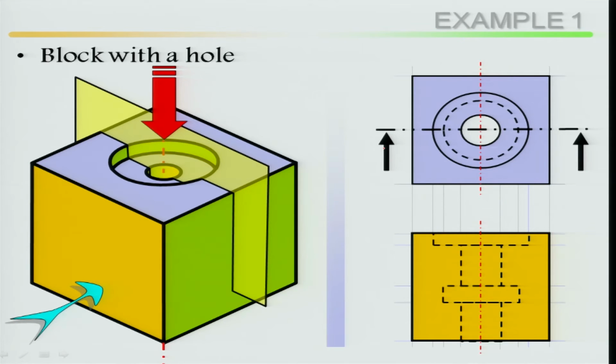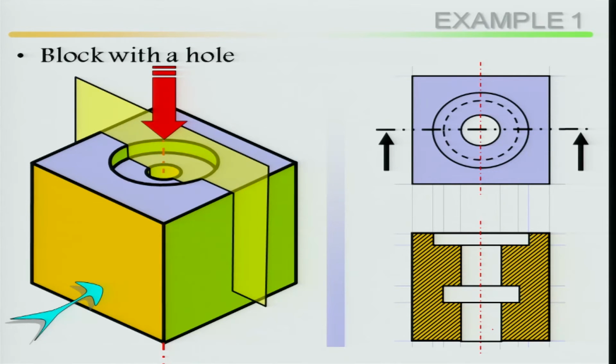So, now this front view, these are all your hidden lines, how it looks inside. There is a hole here, then inside there is a hole, then at the middle there is this, then outer it is this. Now, you are taking out this. What is this material made up of? After this hole, the moment I am doing this hatching, it is made up of steel, cast iron. So, on both the sides the material is the same, that means the entire material is the same, only there is a drill at the top and at the middle.